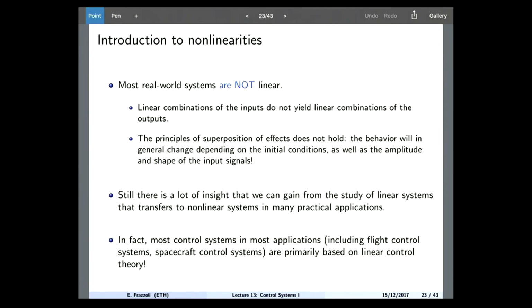Okay, second part of this lecture, we look at how you deal with nonlinearities, okay? So it's kind of funny. You have even experienced controls engineers that say, so we have nonlinearities like time delays. No. Time delays are a very linear effect, right? It's a little bit more complicated to deal with, but it's definitely not a nonlinear effect.